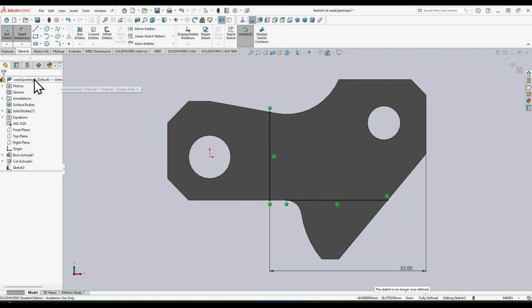It's already black, because SolidWorks understands where that line is in 3D space based on the sketch relations that I made just while drawing it. I'm that talented. So I'm going to exit my smart dimension tool here. Then the other thing I have to do is finish drawing, because when we use a cut tool or an extrude tool, it needs a completely enclosed figure, and all I have right now is a sketch of a line right here and a sketch of a line right here. So I need to enclose this area, and I need to enclose this area.